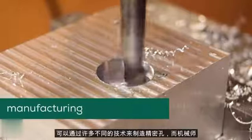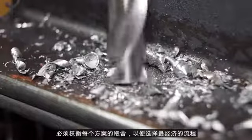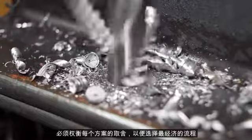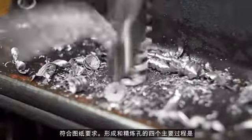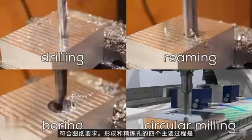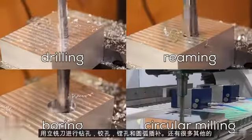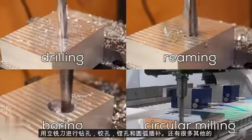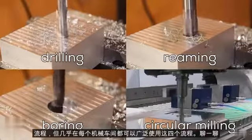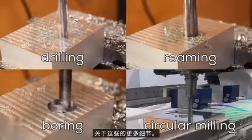Precision holes can be manufactured by a number of different techniques, and the machinist must balance the trade-offs of each in order to choose the most economical process that meets the drawing requirements. The four primary processes for forming and refining holes are drilling, reaming, boring, and circular interpolation with an end mill. There are lots of other processes, but these four are widely available in nearly every machine shop. Let's talk about each of these in a bit more detail.